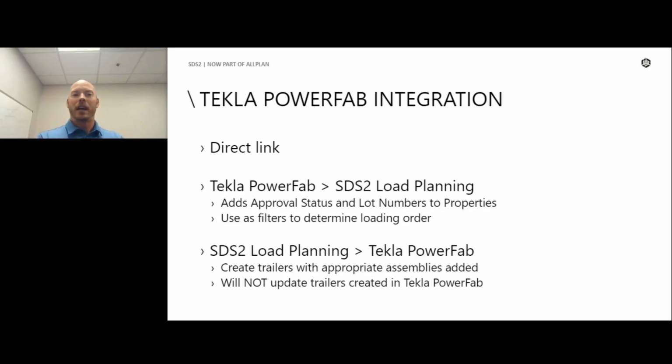Talk about Tekla PowerFab integration. So this is a direct link that we have to Tekla PowerFab now, kind of bi-directional. So the way this is going to work, when you refresh this link to your SDS2 Load Planning project, Tekla PowerFab is going to update SDS2 Load Planning by adding the approval status and lot numbers, if they exist, to the load planning properties. And then you can start using those as filters to determine your loading order within SDS2 Load Planning.